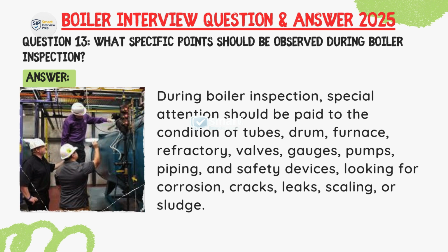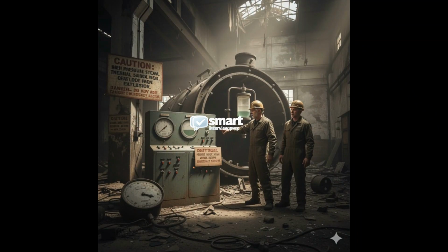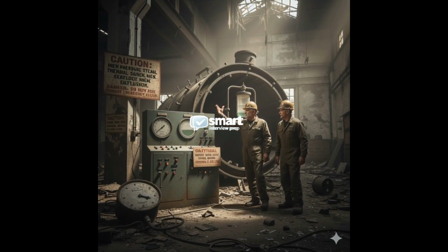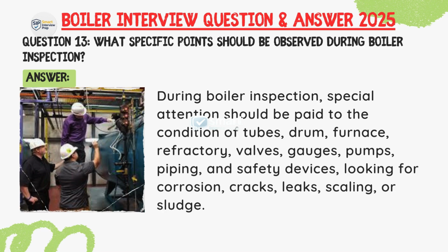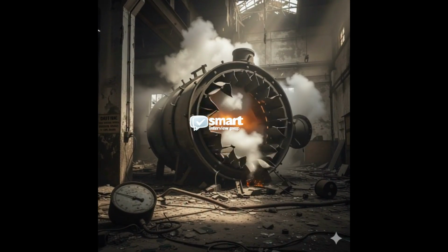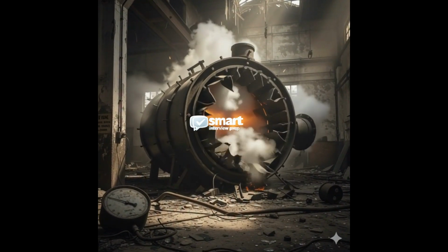Question: What specific points should be observed during boiler inspection? Answer: During boiler inspection, special attention should be paid to the condition of tubes, drum, furnace, refractory, valves, gauges, pumps, piping, and safety devices. Look for corrosion, cracks, leaks, sealing, or sludge.